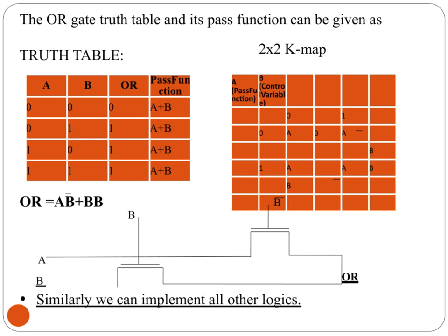The OR gate outputs a high signal, or 1, when at least one of its inputs, A or B, is high. Looking closely at the truth table, whenever A or B is 1, the output is 1. The only time the output is 0 is when both A and B are 0.